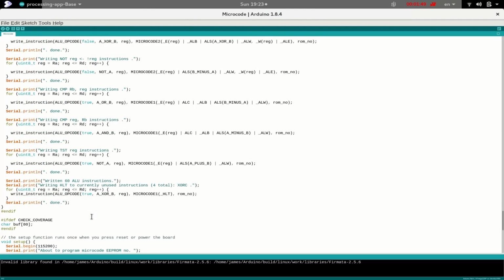And as we've done for all the other classes of instructions, there'll be a few unused opcodes. In this case, there are in fact only 4 of them which we haven't used, and those are the exclusive OR in the operation 3 bits of our opcode with a carry. That would theoretically be what that is. And so that opcode is not assigned, and therefore we implement it using a halt instruction, as we've done for all the other classes of instructions.